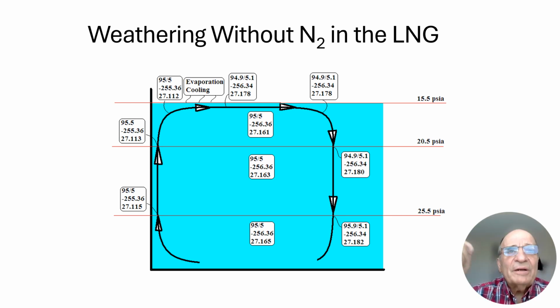This is important when you think about pumping LNG because it's important that this LNG here be at the same temperature as this LNG so that it becomes subcooled LNG because of its pressure head. So for this temperature and this pressure, this is subcooled LNG, and this on the surface is saturated LNG. Remember, to operate a pump, you need subcooled LNG, and that's why if you have a submerged pump, you have subcooled LNG in the pump tube, or if you're taking a bottom withdrawal, you're taking subcooled LNG from the bottom and feeding it to your LNG pumps.